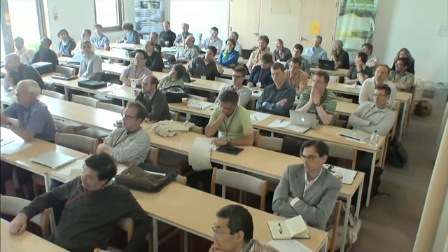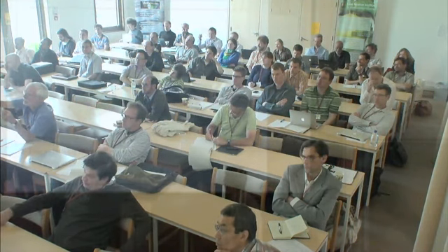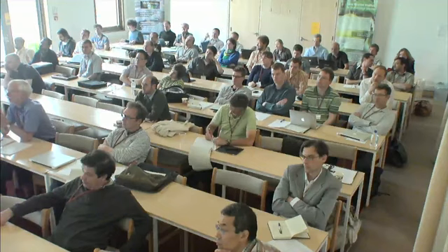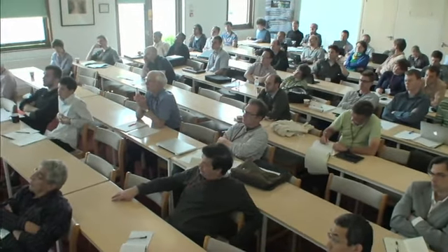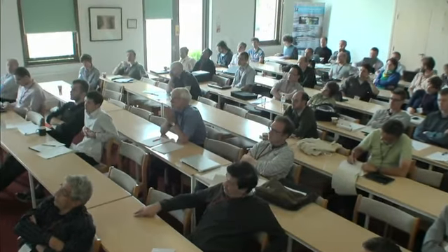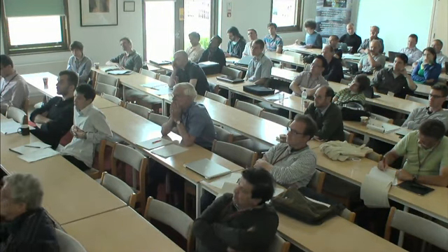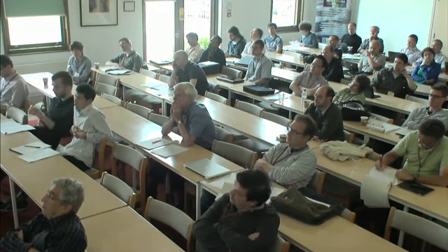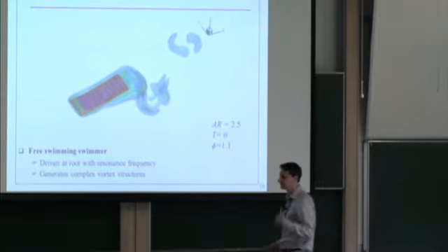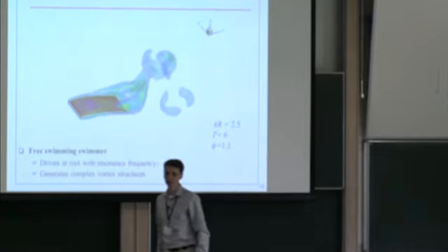Yes, yes. Is that sort of ladder of red stripes which appears every beat something to do with the lattice, or is it just how MATLAB calculates vorticity, because we're still on the lattice, right? So it's just not really smooth. It's a little bit artificial because you need to calculate vorticity at each point, right? And your velocity is discrete. So it's a lattice artifact. It's kind of an artifact of visualization, of the computational lattice.